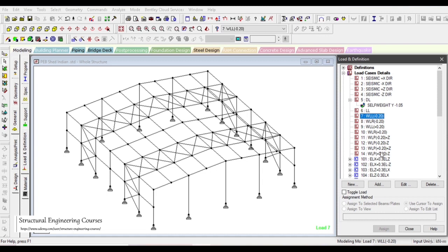But for the American standards, mostly the practice is that we follow the MBMA design manuals, that is Metal Building Manufacturers Association design manuals. You can simply Google that to know about the MBMA manuals. My experience with pre-engineered building designers is that most of them use the MBMA only, because MBMA derives its values from ASCE 07 only.